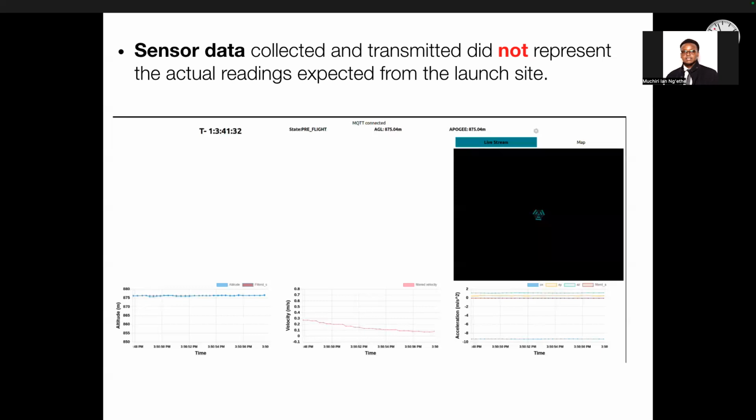So if you take these variations into consideration, the sensor data will not work with the same machine, since the base altitude is calculated when the PCB circuit is turned on. We calculate the base altitude when it is turned on, and the readings were accurate. It was representing around 1300 meters. So all the values that came after, even during the flight, will be below 1300 meters. Hence, it will never detect that the rocket has launched. Next slide.